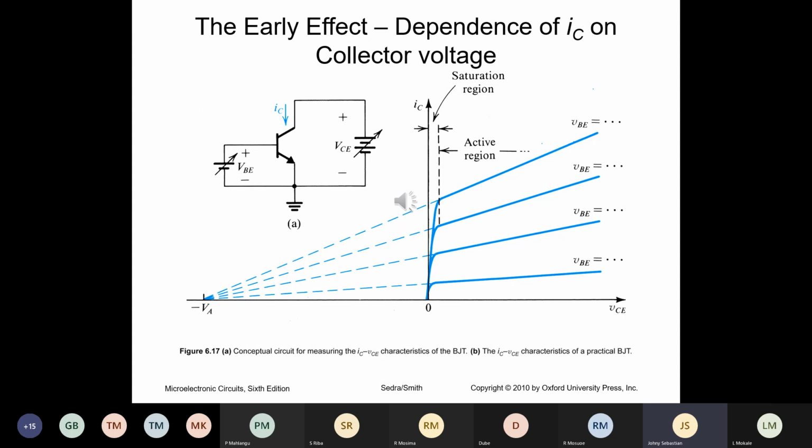That is this battery voltage VCE versus IC, and it is happening at a constant VBE. So with VBE at a certain value, 0.7 like that, you get this graph. You make VBE slightly bigger, 0.72, then you get this graph. The third one, make VBE 0.73 or 74. And the fourth one, 0.76, something like that. So you get different graphs.